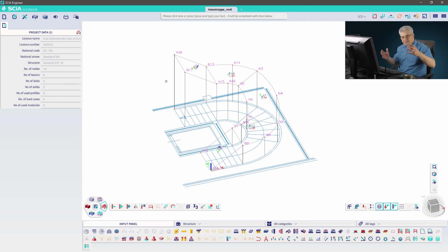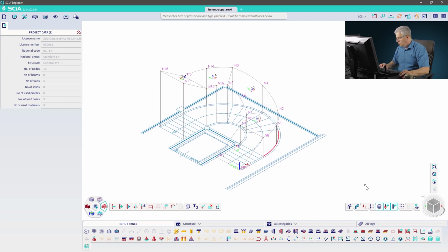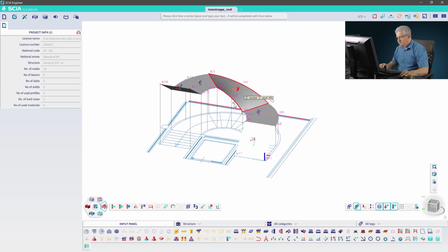And also if you then input, for example, hinges on the lines and not on the full line, then you have to select the start and end point. If you say, for example, half a meter from start, 1 meter from end, and only on a part of this line you want to input, for example, a load or a hinge, then you have to know in which direction this structure is drawn. So, and that's all. This is drawn. So we have also another possibility.